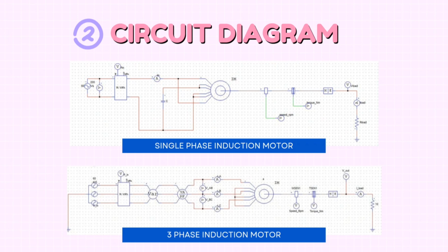The difference between these two circuits is for single phase induction motor, the capacitor is placed in series with auxiliary winding. This single phase induction motor requires a run capacitor to energize the second phase winding, which is auxiliary coil, to create a rotating magnetic field while the motor is running. Start capacitors briefly increase motor starting torque and allow a motor to be cycled on and off rapidly.